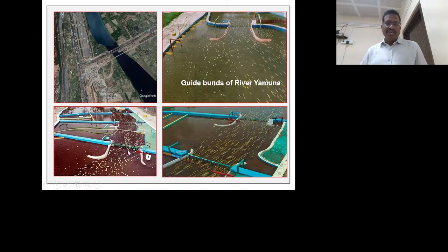So you can see here there are continuous bridges. These pink color are the guide bunds we have suggested, and flow is only flowing through these bridges. You can find this channelization of flow. You can find this velocity is only in this direction. Water is there but stagnant on this left side, there is no flow here, only flow you can see in this channel.